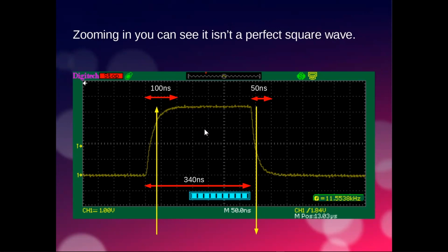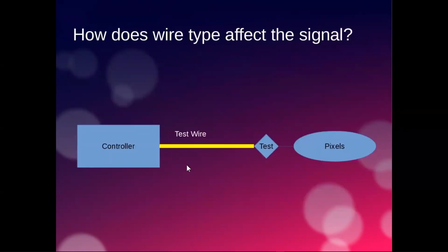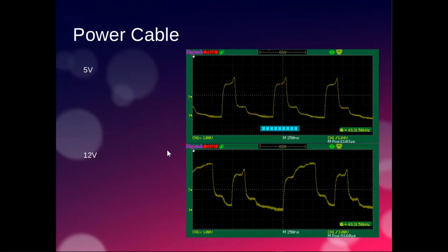Now, why is this a big deal? Well, this is a big deal because the signals are not as clean as this, particularly not after you've got a long piece of wire. So let's look at what happens if you set this thing up just as we had before, but instead of just testing the voltage here, let's put the oscilloscope on here and see what our signals look like. And that's what they actually look like. And that's pretty damn ugly.